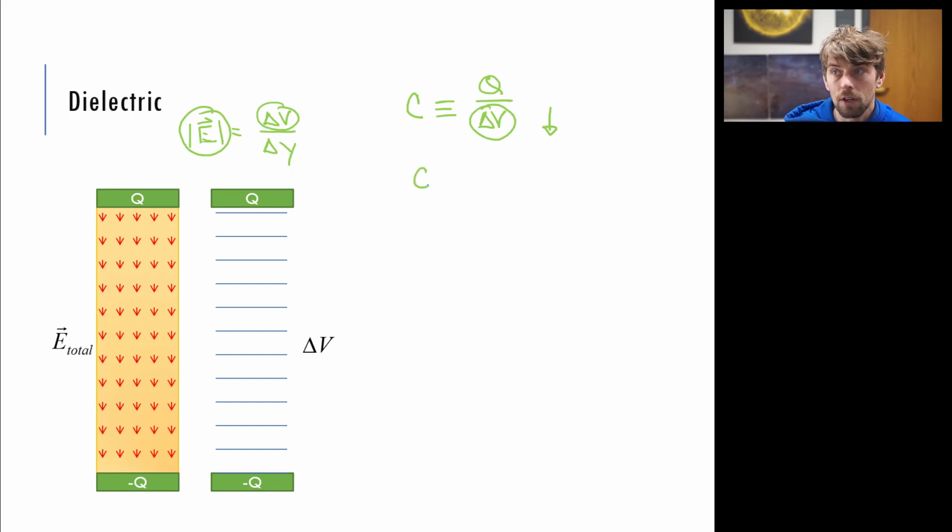By inserting the dielectric, our capacitor is able to store more charge, assuming that everything else stays the same. So the plate area stays the same, the distance between the plates stays the same, everything stays the same. Comparing the air-filled capacitor to a capacitor that has a material, the one with the dielectric material can store more charge. That's particularly useful when space is of concern.